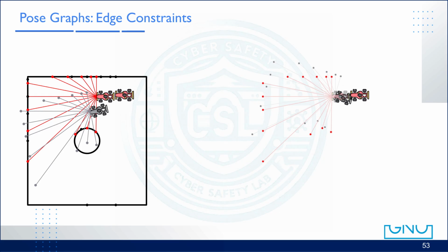In slide 53, you can see the poses moving into alignment as the constraints pull them into their corrected positions. Does this look familiar? This is exactly the same scan matching problem we saw earlier. In the picture, multiple LiDAR scans from different poses are stacked without proper alignment. The key idea is that all of these mismatches become edges in a pose graph, represented as tension between nodes. Later, during optimization, these tensions determine how the poses should move to satisfy the constraints we define.